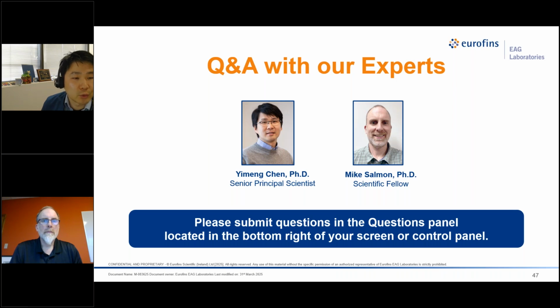So first, you should collect data at the best quality in the mass spectrum, like improving the mass resolving power. To do that, you usually need to run the specimen at a lower temperature using a lower laser pulse